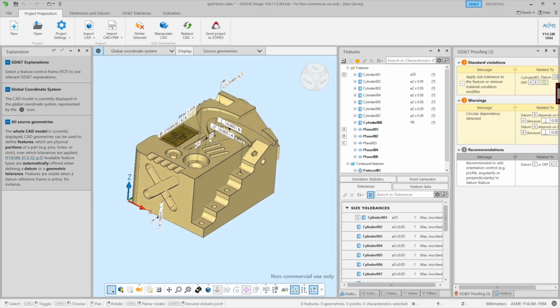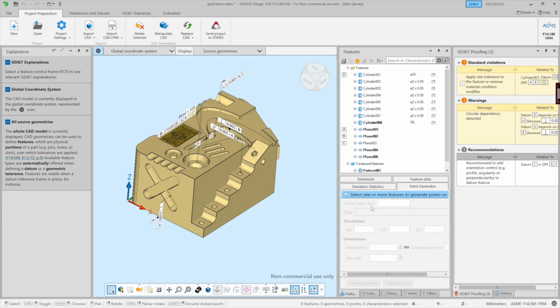So when we bring it in, we can see the model, we can see all the dimensions, we get the list of features, all our tolerances, we can simulate data points, so we can generate data points on the model and induce error to try and simulate manufacturing error to see what the effects are on the results in our GD&T. I see, okay. So you can find out what might happen to your process before you ever start cutting apart.